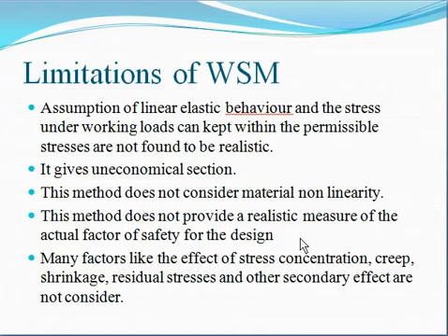Like stress concentration. What is the meaning of stress concentration? It means the concentration of stress at a particular point in the section. At some point the stress concentration is less and at some other point the stress concentration is large or more. This effect is not considered by this method. Second is creep. Creep is nothing but the time dependent deformation of the structure. As the time passes, the deformation goes on increasing. That is nothing but the creep. This point is also not considered by this method.